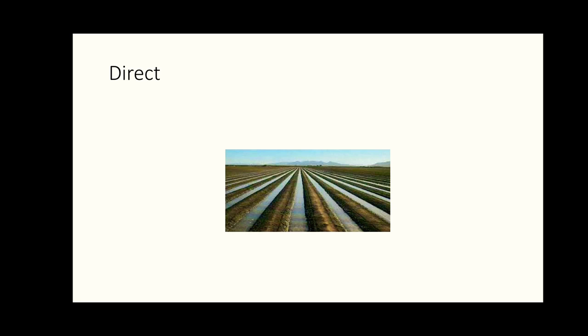So direct irrigation, which is river canal irrigation, is of small magnitude, because there are no rigid controls over the supplies. Only one or two main canals may take off directly from the river, and cross drainage works are constructed wherever natural drains or distributaries cross the canal. In a bigger scheme, there may be a branch canal taking off from the main canal. Otherwise, there is no such need.